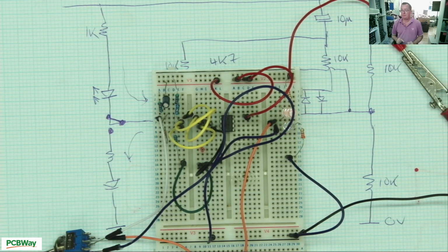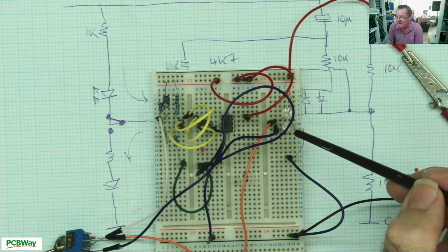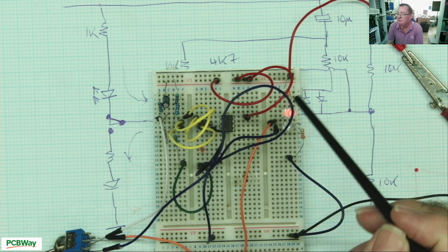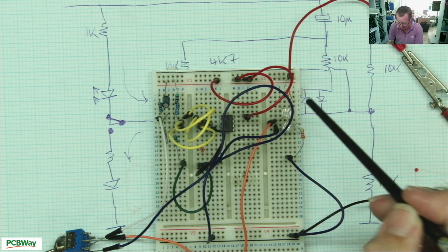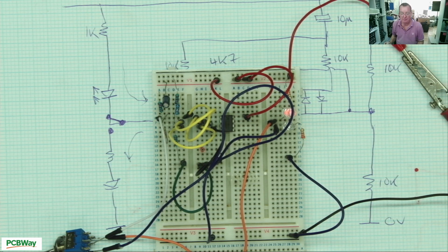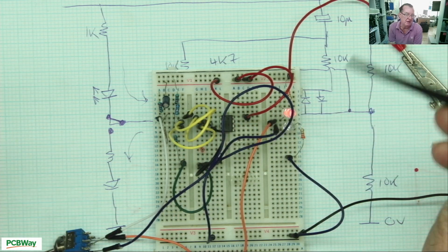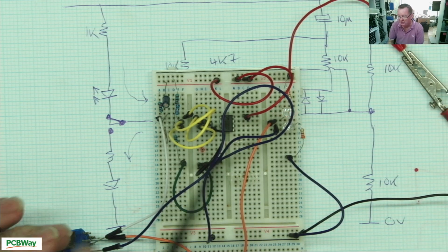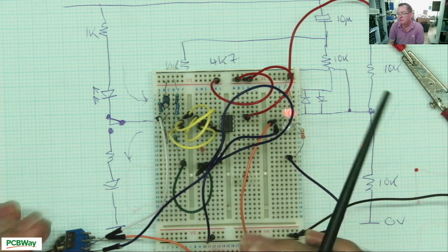Yeah. And that leads us to an interesting choice. So we could take out this bottom LED and the resistor and the switch. Okay, just leave that one wired in, and then in actual fact this will test both comparators and op amps on the one circuit. Okay, and we just replicate it 2-4 times. We can do dual and quad. So our tester circuitry now is very, very simple, and we could do that, but I think it's advantageous to leave the switch in, and we'll need a 4-pole changeover for 4 circuits.